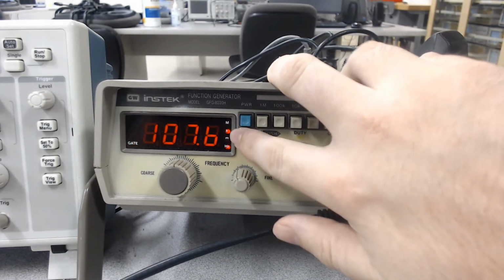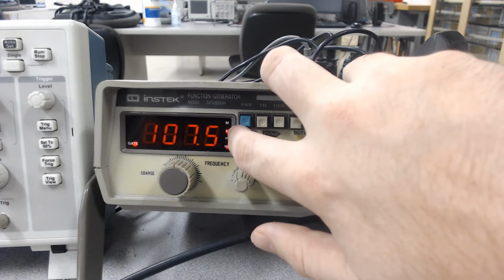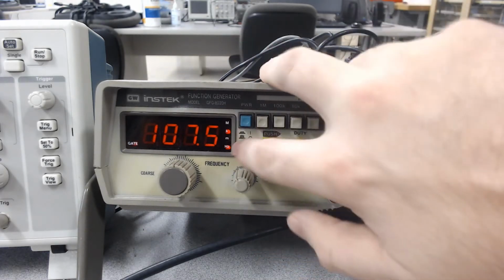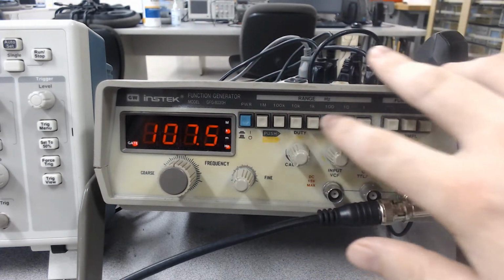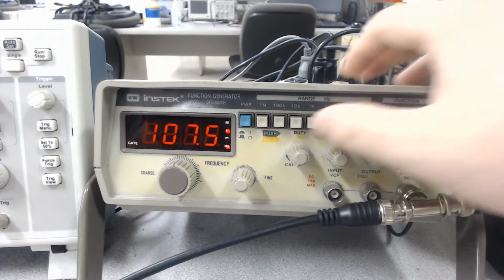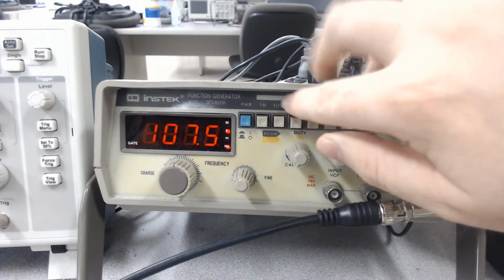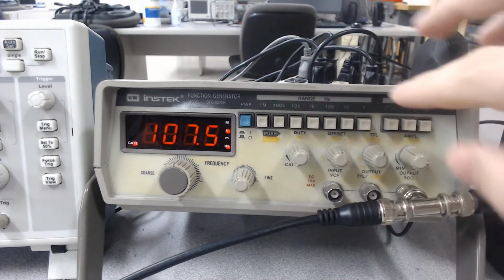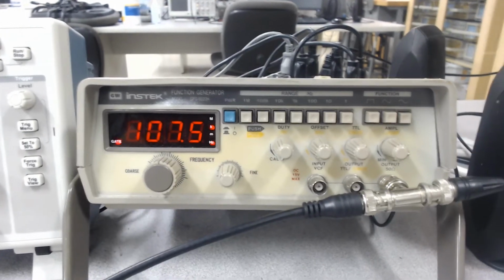Make sure that whenever you're reading the frequencies, you pay attention to this little red dot here. So this is actually 107 kilohertz instead of just 107 hertz. The numbers up here, even though you can see them, are not multipliers. So this is not 107 times 100K. This is just 107 kilohertz. It's not a multiplier, it's just a range setting to get you in the general range.